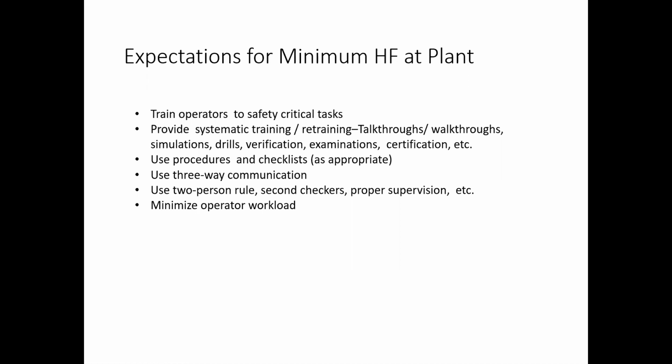Three-way communication. This is a huge one when you see operators actually doing tasks, where one will say, open valve X to 20%. The other operator will say, opening valve X to 20%, valve open to 20%. The original person will say, confirmed, valve open to 20%. It's that three-step process to make sure that there's total understanding. If you ever get the chance, it is really neat to see it in action with people who know what they're doing and have done it a lot. It's really, really cool.